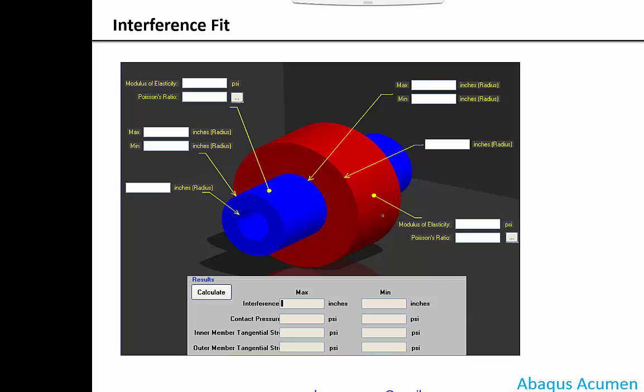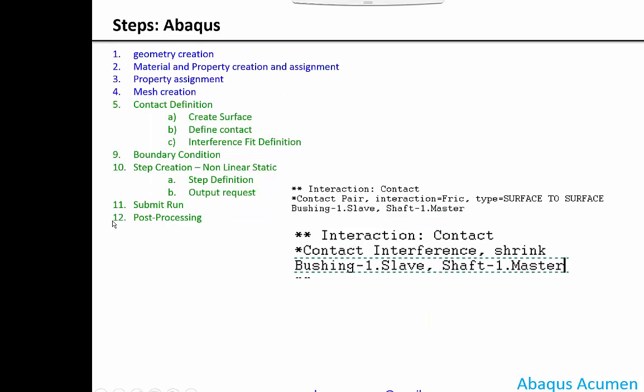You can use a simple Abaqus axisymmetric model, and you can build a DOE, design of experiment, or generate a lot of data to find all these answers accurately. So that's what we are actually going to do. The other learning we'll have is how to model interference.